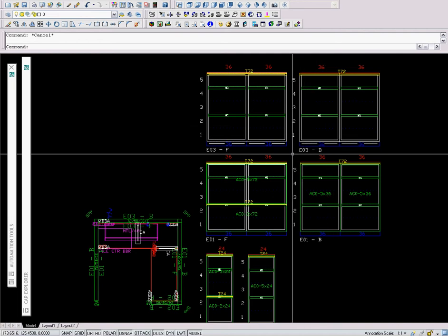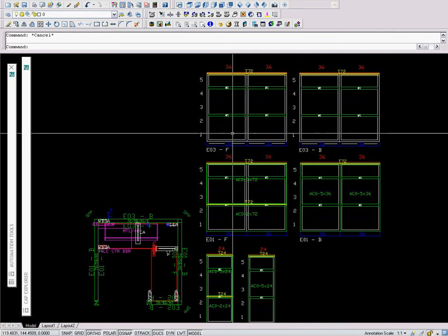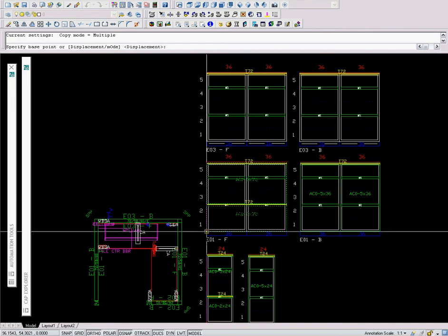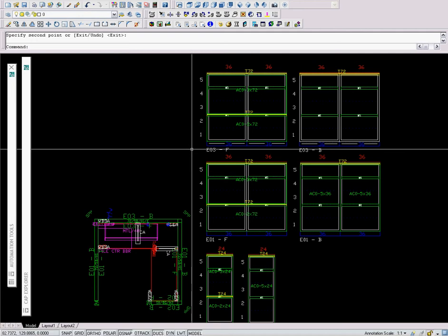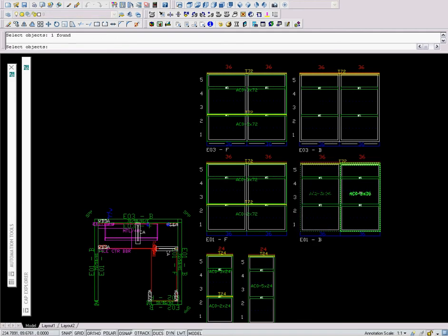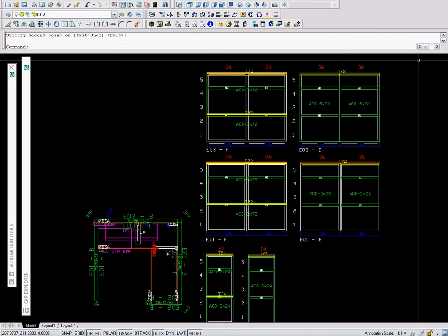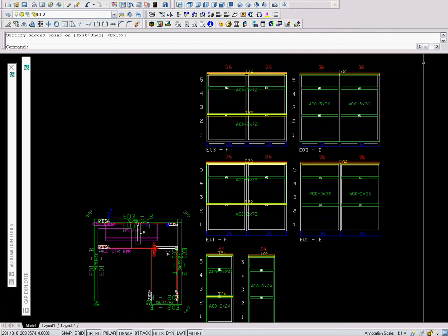Notice that the runs have white lines in the wireway covers, and that's what you see in blue. I'm now simply going to kind of cheat a little bit, save some time, and I'm going to take that elevation on up. Also, I'm going to cheat for the other side. Now, the reason I can't use the E01 elevation is, keep in mind, the frames have power in them now for the elevation that I just changed. So with that, that means my specification is going to be different when I run a bill of materials.